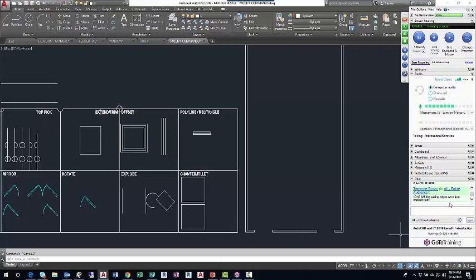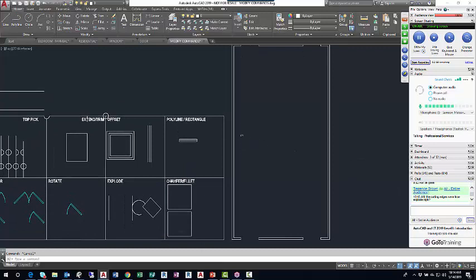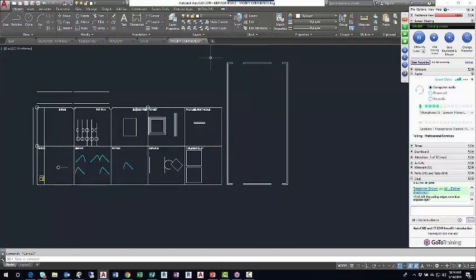Okay. The cutting edges were from, yeah. So Terrence says the cutting edges were from explode, right? Yeah, I would say you could absolutely say that. Prior to exploding the rectangle, I could only offset additional rectangles. So when it's exploded, the polyline, I was able to offset individual sides to make those cutting edges.